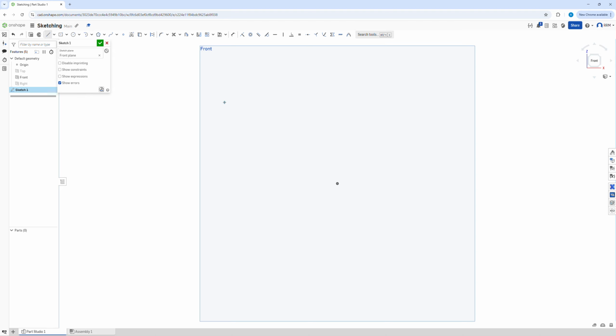So we've got the line tool where I can just click once, drag the mouse, click again, drag the mouse, click again, etc. Okay, and that allows us to create a simple blue line. I can press escape to get rid of that, and I have my line like so. I could also use, say, a midpoint line. The drop down, I click once, click again, and you can see that I have now got a symmetric line from the point where I first clicked.